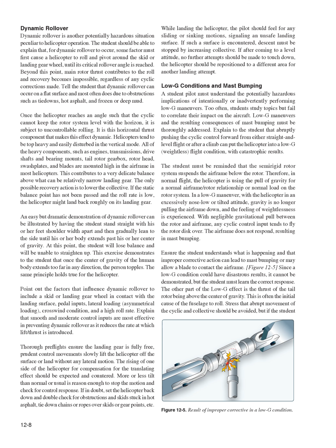The only possible recovery action is to lower the collective. If the static balance point has not been passed and the roll rate is low, the helicopter might land back roughly on its landing gear.